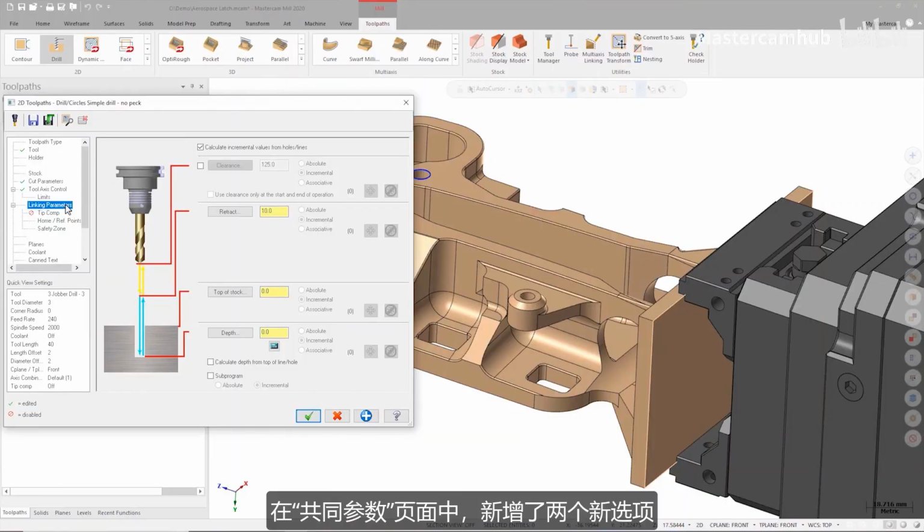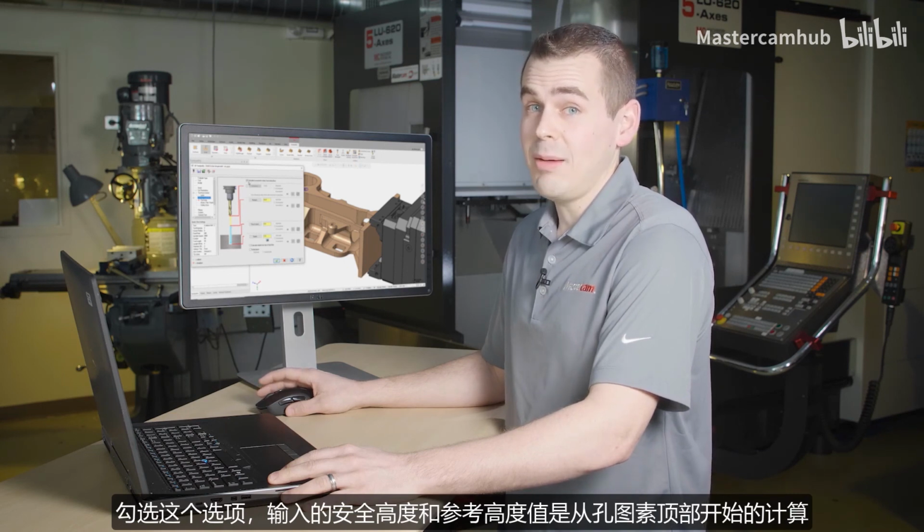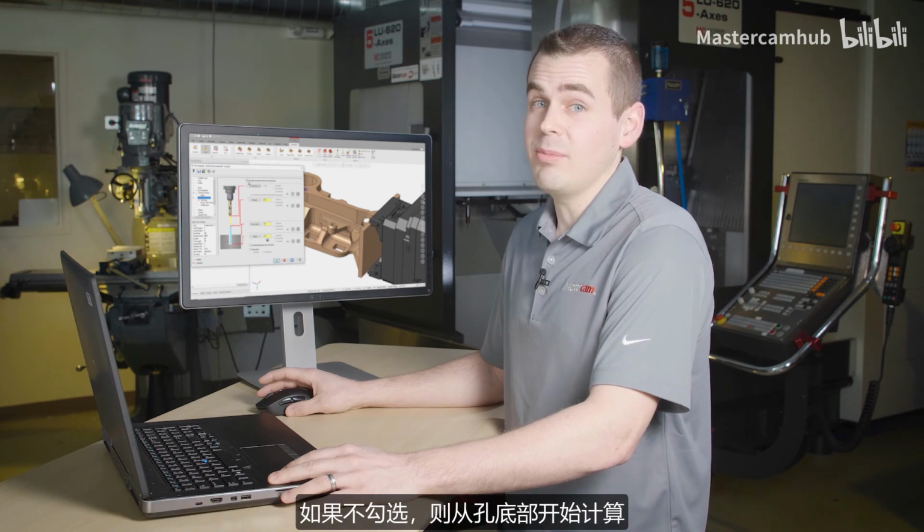On the Linking Parameters page, there are 2 new checkboxes. At the top of the dialog, there's Calculate Incremental Values from Holes and Lines. What this means is that the incremental values for clearance and retract are measured from the top of the hole geometry, while the depth is measured from the bottom of the hole geometry.